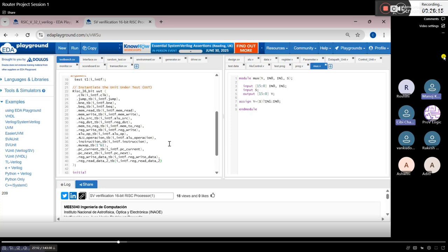And as I told you, while instantiating, we have two types of port connection: one is port connection by name, and one is port connection by order. By using this, we will connect our ports. Connecting our ports means nothing but this instantiation of our design. Inside that we have our signals, and the signals should be connected. So for that connection, I'm telling.